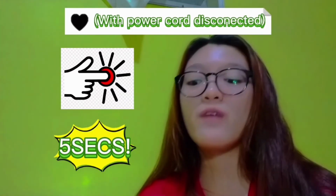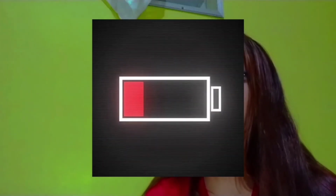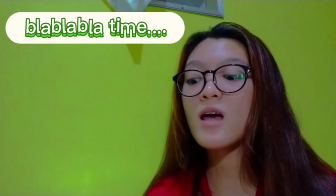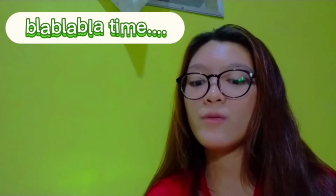So third, if you are finished disconnecting everything, push the power button for 5 seconds. The computer can still hold power even with the power cord disconnected. Pushing the power button drains that power. Very important. This is just like your TV, because most computers, TVs, stereos or other gadgets are actually powered off, but there are small circuits on them that may be active, used to sense when you want to turn the device on.